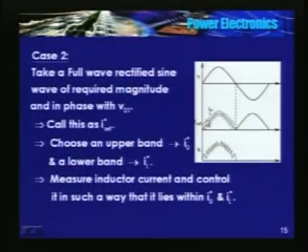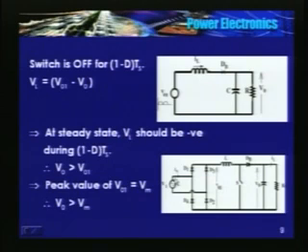I have taken a hysteresis band, so this technique is also known as the hysteresis current control technique. Current is controlled within the hysteresis band, and the inductor current looks like a rectified sine wave. This inductor current is the same as the source current. Whatever current flows through the inductor should come from the source. So if it is a rectified sine, the source current is a sinusoid, so this Is is in phase with Vi. Therefore the displacement factor is unity.